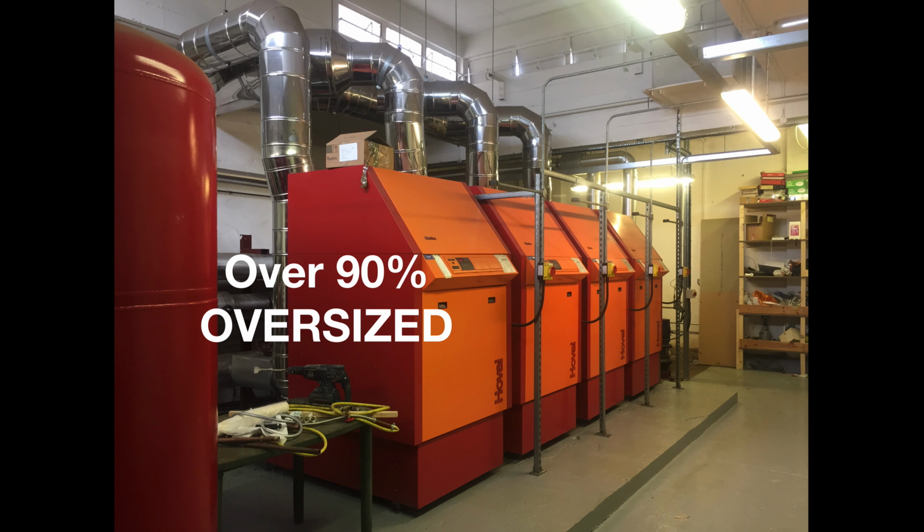This particular cascade is actually 5.4 megawatts, so 5,400 kilowatts. Now this is feeding, I think, about 130 flats, so they're quite small flats. If I just type into my calculator 5,400 and divide that by 135 properties, that's basically 40 kilowatts. If everybody wants to play with their calculators, you can see that's 40 kilowatts per small 2-bedroom property. And we all know that they won't all be using that 40 kilowatts at the same time. So we can see that this is massively, massively oversized.